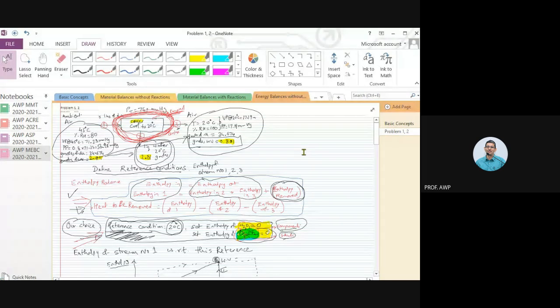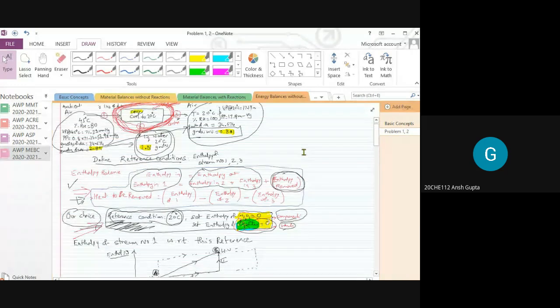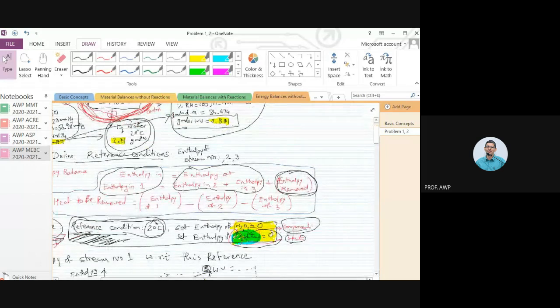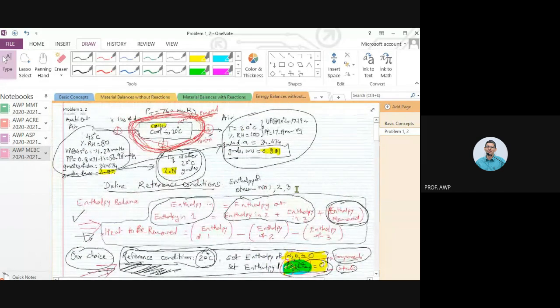Yeah, so when you solved in both the methods, we never considered the dew point. Is it because we consider only the final state and initial state? Correct. Enthalpy is a state function. I don't care what the dew point is, as long as I have inherently used the dew point in calculating that 2.811 gram moles come in and 2.01 gram moles of water condense out, and 2.801 gram moles remain in the vapor state, right? The dew point is automatically considered. The dew point is about 20 degrees centigrade. That's why it is getting condensed.